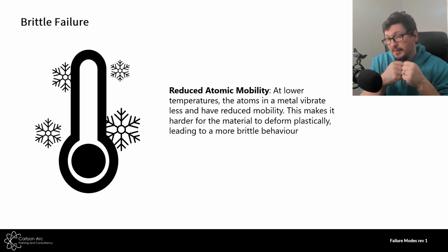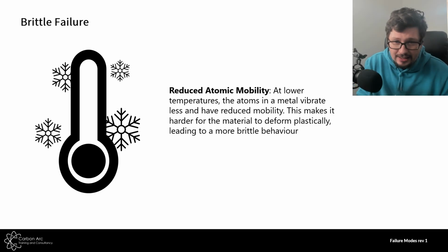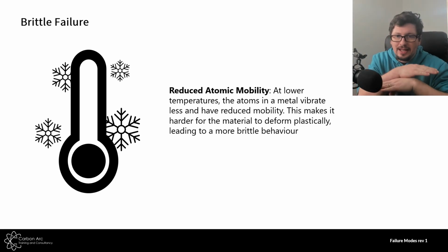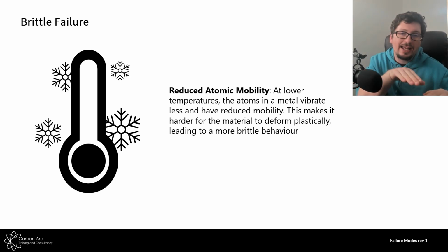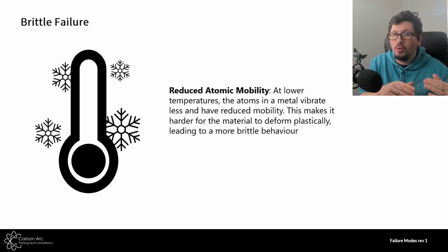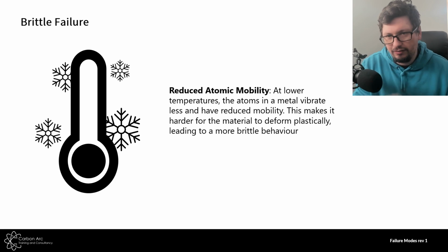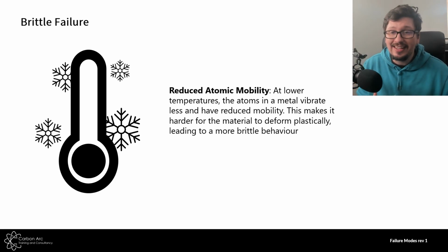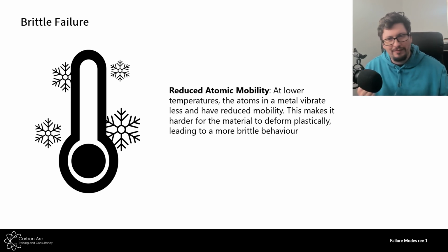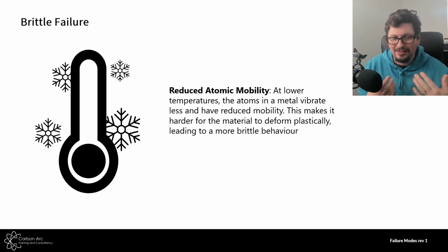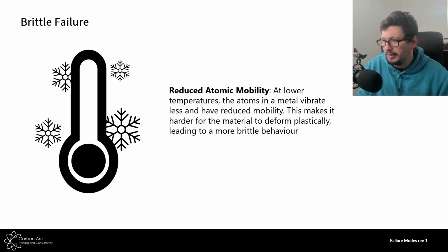So it's going to take more energy, but the way it behaves when it fails tends to be a splitting, a cracking along grain boundaries or directly through the grains in an instantaneous failure. Well, when we say instantaneous, we mean at the speed of sound in that material. So, you know, fast enough not to really care. It's fast, okay? For us, it's pretty much straight away, okay?